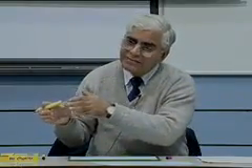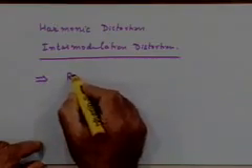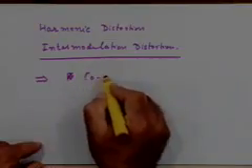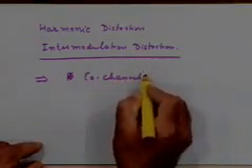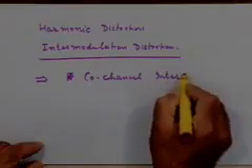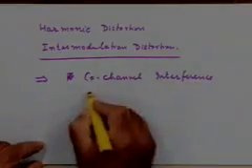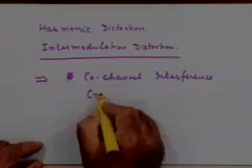Suppose you are allotted a certain frequency band to work with, you are transmitting outside that band. Your received signal contains components outside the band. If your receiver was now trying to look for a signal in that frequency band, it will not only see that, but will also see some components from this, and this will cause a kind of crosstalk. It's also called co-channel interference, or sometimes simply called crosstalk.